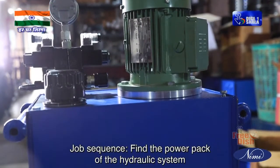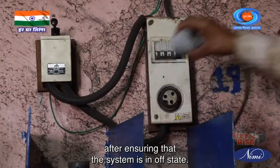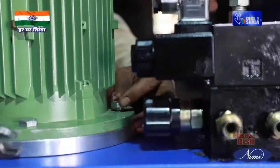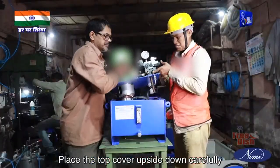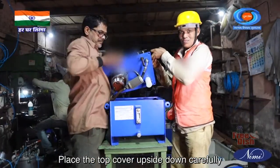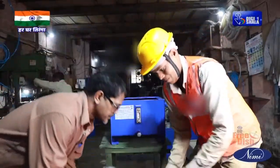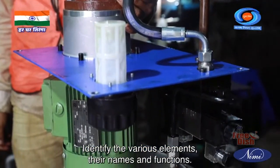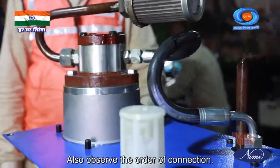Job sequence. Find the power pack of the hydraulic system after ensuring that the system is in off state. Unscrew the fastening bolts on the top to remove the top cover. Place the top cover upside down carefully so as to not damage any of the pipes. Identify the various elements, their names and functions. Also, observe the order of connection.